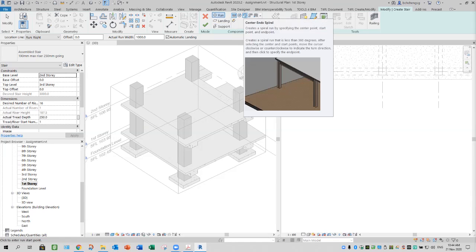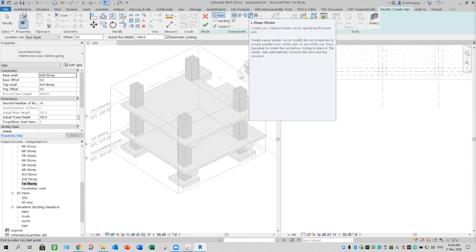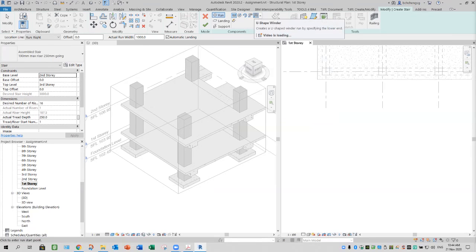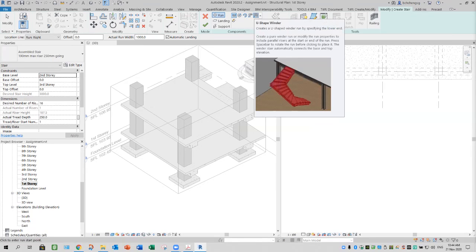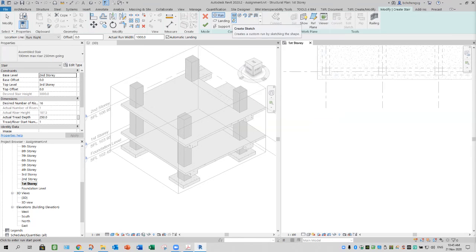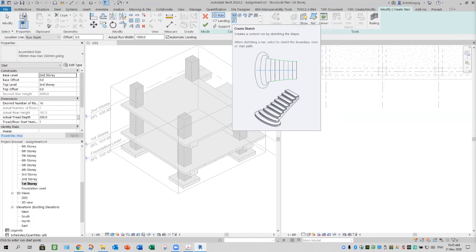You can have that. This is for those staircases normally at the side where space is quite cramped and you need even a landing to also be a staircase or be a step. So it looks something like this. In US terms, they call it a winder. This is a U-shaped winder. Okay. This is how it's built. But normally in real world design, we don't design something like that. It's quite easy to trip and fall. Very scary. This one is for manually drawing yourself. Yeah. Landing.